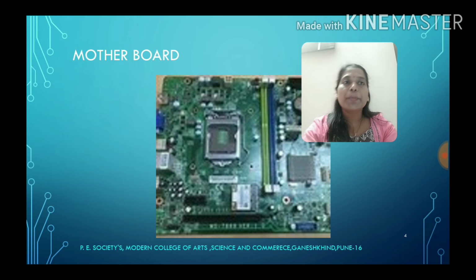But along with this, as these four blocks have to work together, a synchronization of the operation with a common time reference is required, and therefore the motherboard also includes the oscillators, timers, counters. Along with that, to handle unwanted procedures, that is interrupts, interrupt controllers are also implemented on the motherboard.